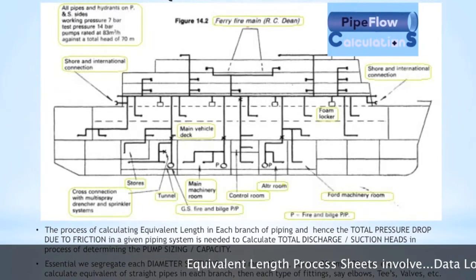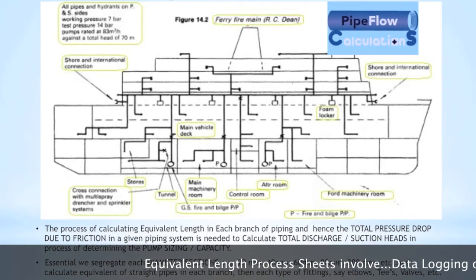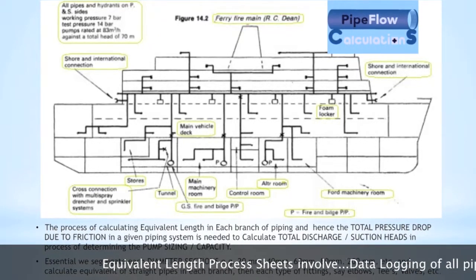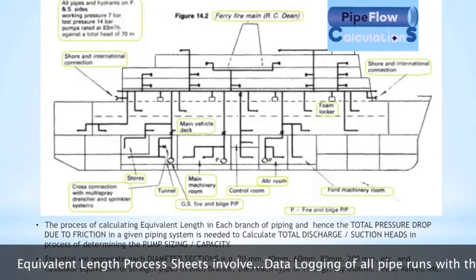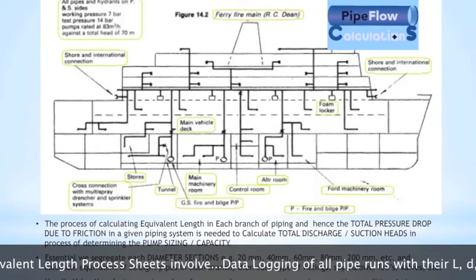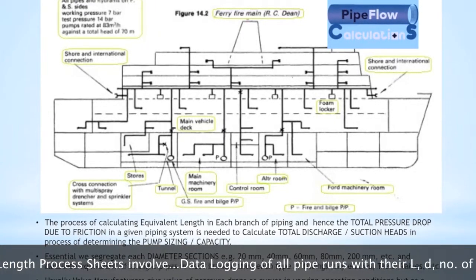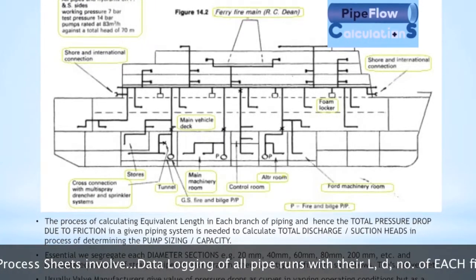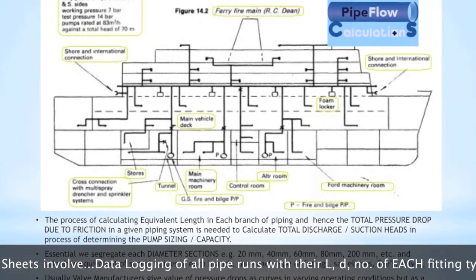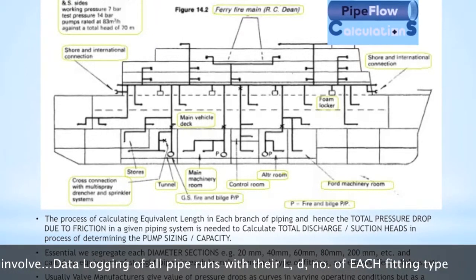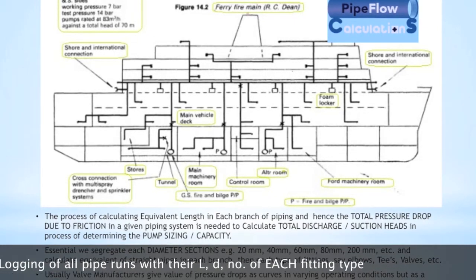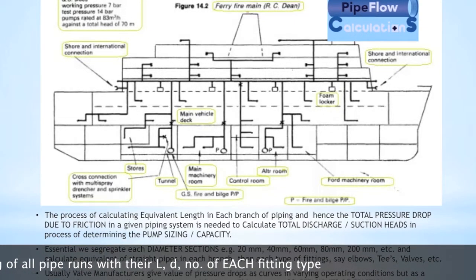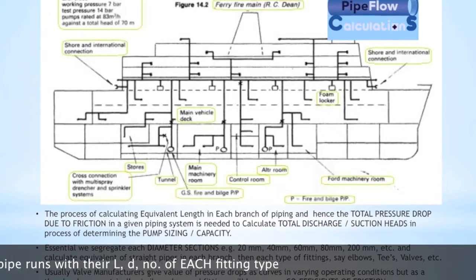With this, what typically you will do if you are sitting on the design table is that you will just take each and every little section. A little section means the point from where the line is branching out from the main discharge line to that point of discharge. And for each of these, you put the values of L and D on an Excel sheet. You just calculate the number of fittings and the length of the pipe. I will show later on in an actual calculation.